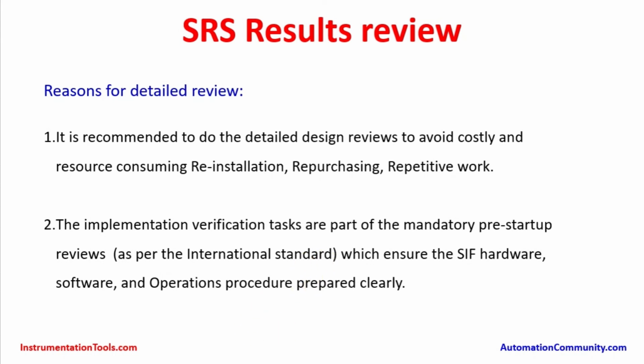The safety instrumented function hardware, software and operation procedures are to be prepared clearly, to avoid any mistakes and any rework on the safety instrumented system installation, testing and maintenance. So at the beginning of the engineering phase, these are the details to be taken care of and properly entered into the SRS form, so that all the installation and testing will go as per the procedures, which may also eventually reduce the rework.